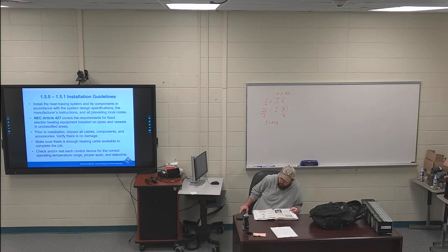And the second bullet point on 17, first sentence, goes along with that highlight. After the installation is complete, retest the cables electrically the same manner as pre-installation testing. So all they're saying for that highlight going back to 15 is you're testing the cable for continuity and electrical insulation before installation and after installation. Just want to make sure that you guys know that.